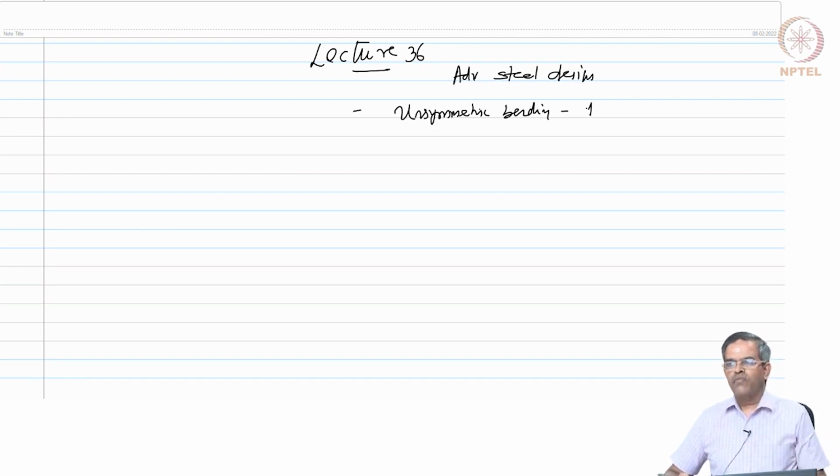Then for form dominant design, we understood that stability, which is one of the modes of failure, is important to assess, and we developed stability functions for various application conditions of axial compressive load, axial tensile load, and so on. And we did some problems and used MATLAB intensively to find out the critical buckling load, so that I can assess stability of these systems.